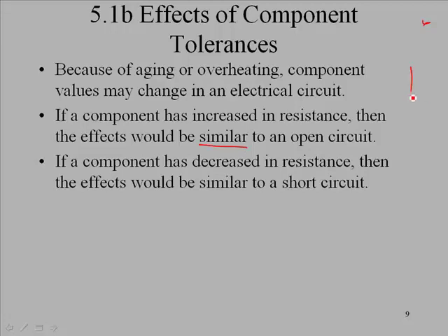Remember, when you have a circuit and there is a complete open, then the resistance across the component will be infinite. Now in this case, the resistance has increased, so the resistance has gone up, but not to the point where it is infinite. If a component has decreased in resistance, then the effects would be similar to a short. And again, the same idea with a short. There is going to be zero resistance. In this case, if the component value has decreased, then we just have fewer ohms than it should be, but it is not to the point of being a short.